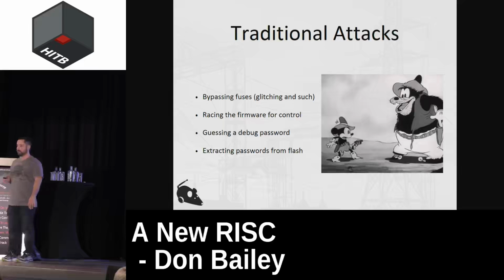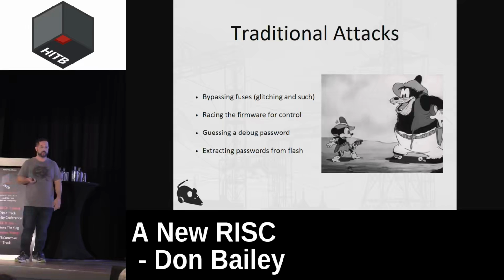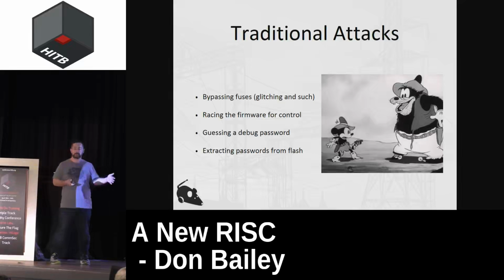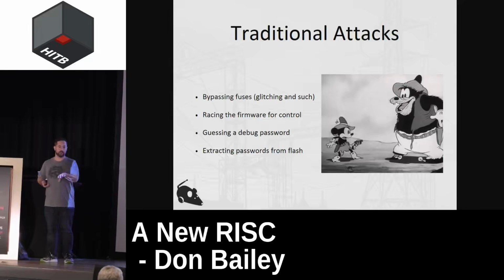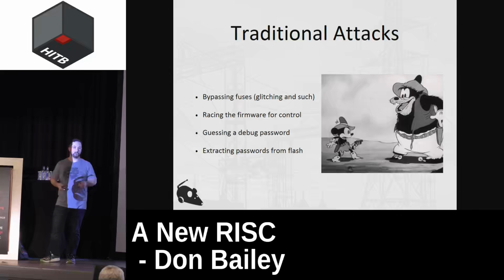Really all you have to do is just guess whatever password's being used. And in most cases, the password is actually stored somewhere in Flash. So you can just extract Flash by attaching a NAND reader or a SPI reader or something in that case, and then finding basically in memory where that should be stored, and then using that password over a serial port.